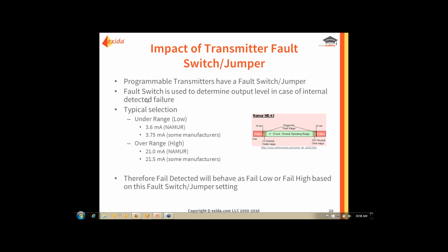It's assumed that your trip limits are set appropriately according to that safety accuracy. So in that case, it would not have an impact. If you have very narrow trip limits, then a signal that becomes a little bit less accurate could definitely be an issue.